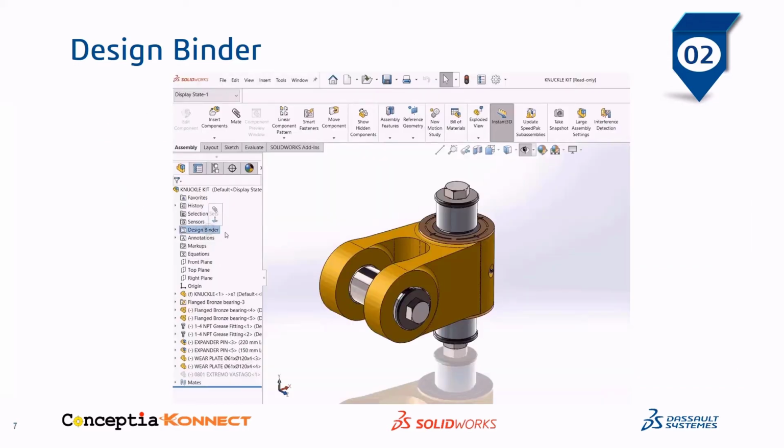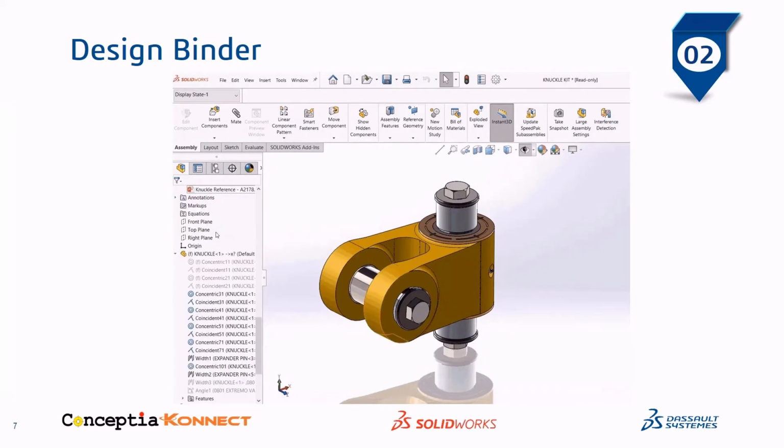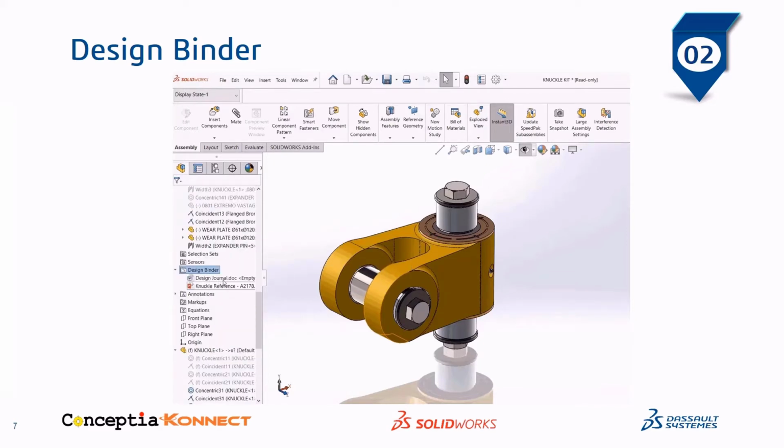All you have to do, right click to the Design Binder, select Add Attachment, browse your file, go to the desired location, select it, select OK. Now the reference file will be added to your Design Binder. So you can add all your non-CAD data in the Design Binder of the 3D model.